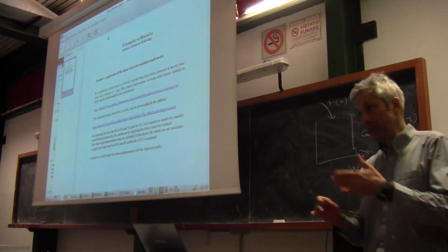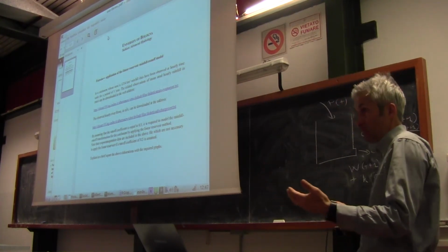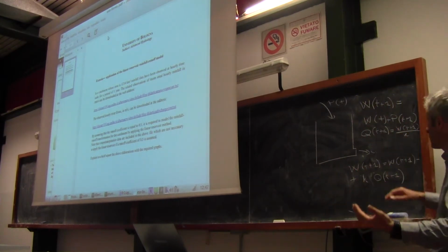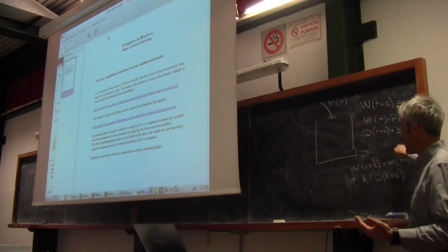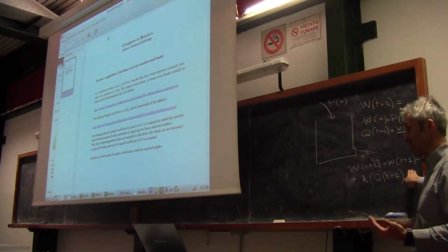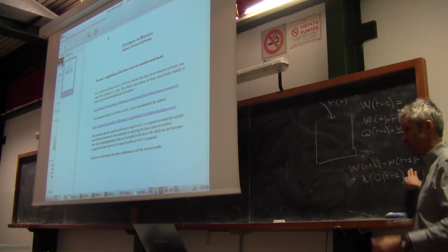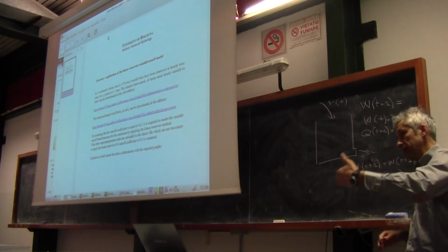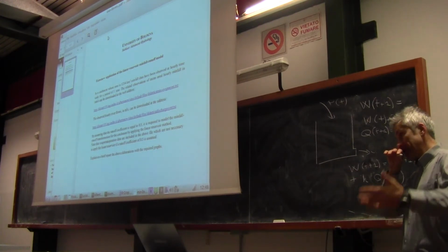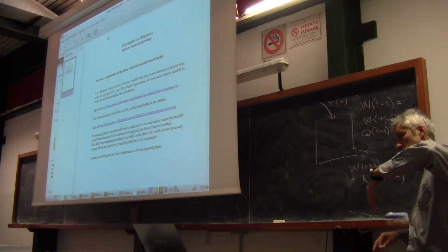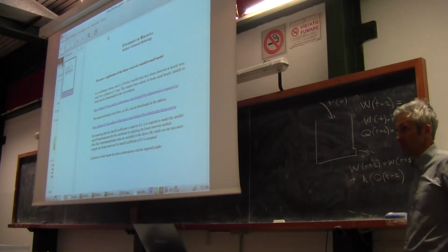So you understand what I did? I started from the previous storage, I added rainfall, I computed the outflow, and then I am updating the storage by subtracting the outflow, because at the same time you have something entering into the reservoir and something going out.